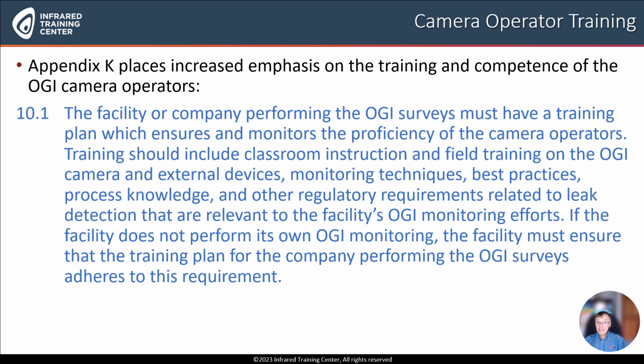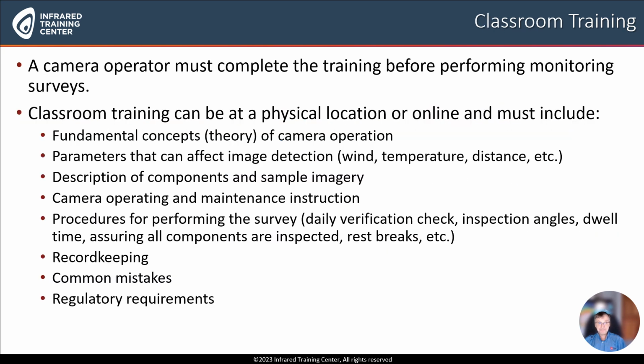And if the facility does not perform its own OGI monitoring, the facility must ensure that the training plan for the company performing the OGI surveys adheres to this requirement. So this is not only for people who have their own OGI programs, this is for folks who hire consultants in. So the consultants performing these surveys must assure to the people who hired them that their training plan makes this and their inspectors are qualified.